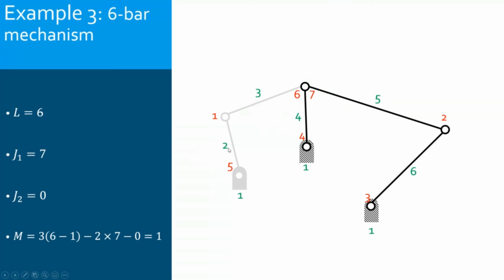So just by having one input, I have a predictable motion for all the links. And this is just one input, predictable. It means that the mobility again is 1. So this is just to interpret and to check that our equations are giving something logical.